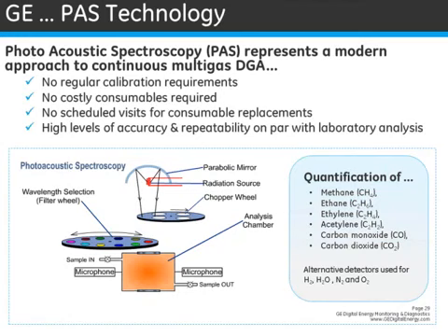PAS has some very significant advantages. So in general, infrared systems, and there are many types out there, have the ability to operate for long periods completely autonomous of any user interaction. And this is a key requirement of any online monitor. Because IR systems do not typically require any carrier gases or other consumables, they can have a long service interval, 7+ years, for example.